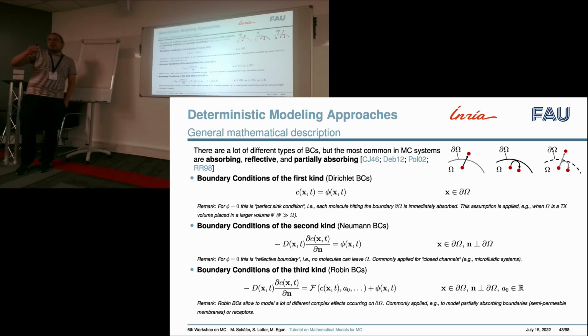Yeah. So somewhere there is the coupling, and especially as what we considered was this transition between fluid and air media, then you might see this more as coupling conditions because we couple two systems with each other. So we have this bounded domain for the fluid, and then we might have a bounded or unbounded domain for the environment. And then these boundary conditions are more like transition conditions because the output of one system is the input of the next system, and there these effects can be included.